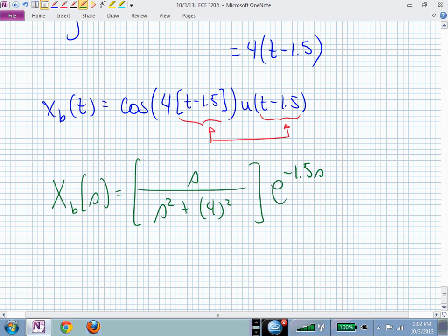And that's now our Laplace transform of that weird-looking time-delayed cosine waveform that had a frequency of what? Well, if I just gave you this Laplace transform and said, what's the frequency of the cosine or sine wave associated with this transfer function, you should be able to tell me. You can say, oh, the poles are at plus and minus j4. Your frequencies are 4 radians per second. So your sines and cosines, whatever those would be, are going to be 4 radians per second.